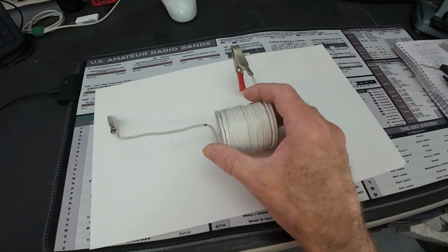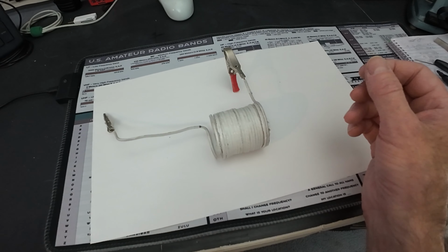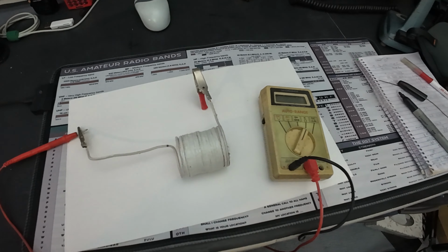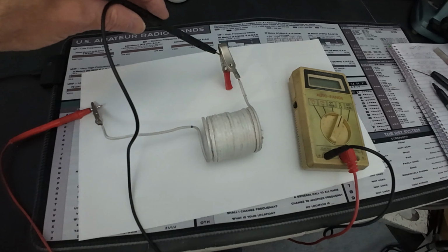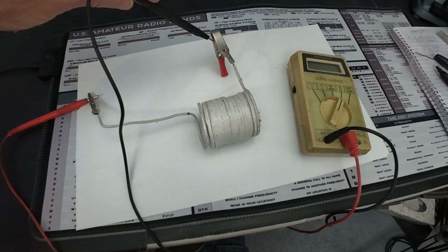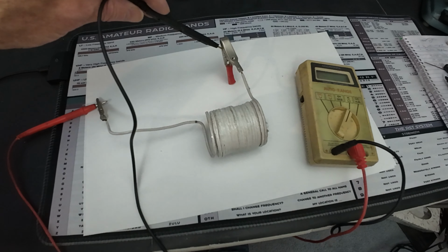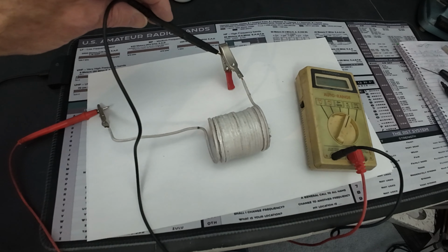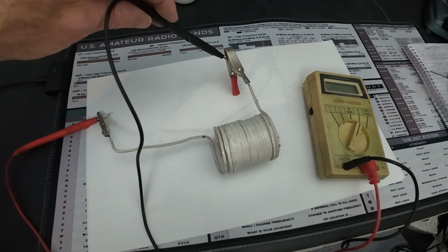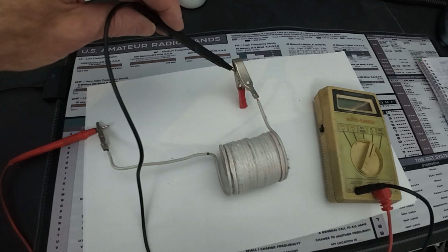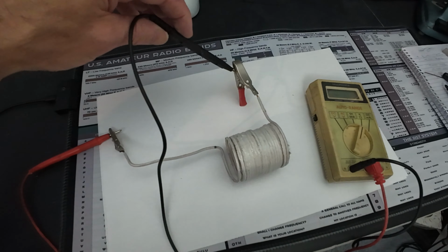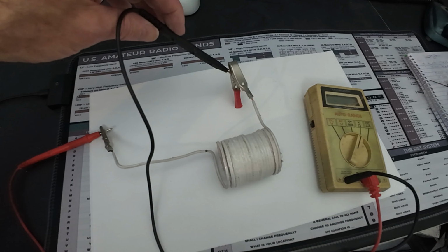Because something like this resists the flow of current initially, if we were to take a voltmeter and put that voltmeter across these two coils and connect it to a battery and flip the switch, what you would see is initially there would be a resistance to current flow. You'd have instant voltage, but no current flow. So in this case, the inductor acts just opposite from a capacitor. In a capacitor, current is ahead of the voltage by a certain amount. If it's a purely capacitive circuit, it'll be ahead of it by 90 degrees.